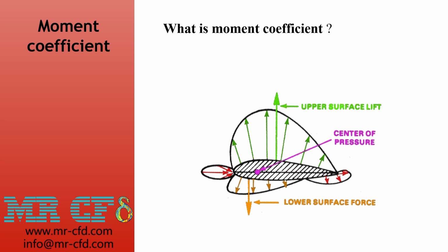So this should be a change in the pitching moment of the wing about the CG rather than the AC. The combination of the two concepts of the aerodynamic center and the pitching moment coefficient makes it relatively simple to analyze some of the flight characteristics of the aircraft, such as dynamic stabilities, which can be calculated with CFD, and we are going to discuss them in sessions ahead.